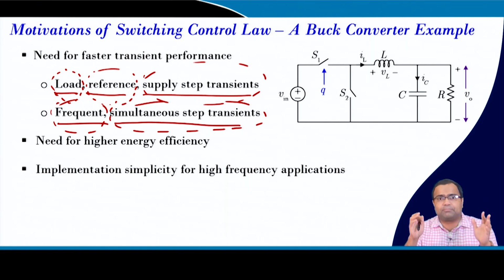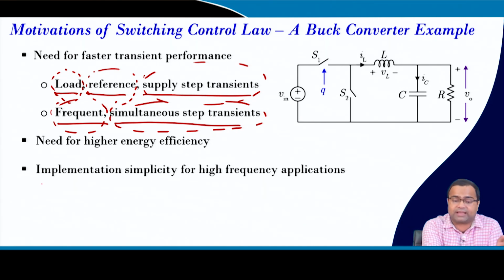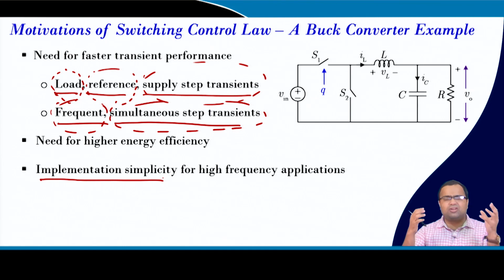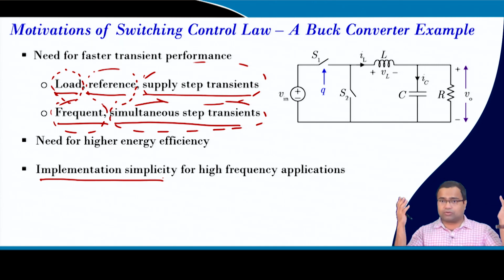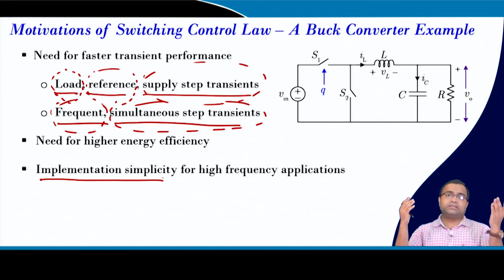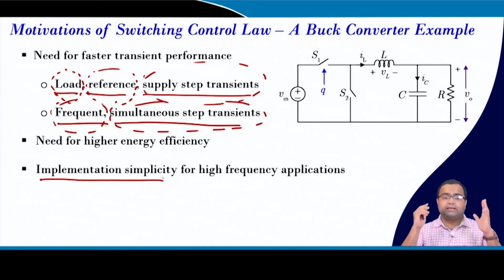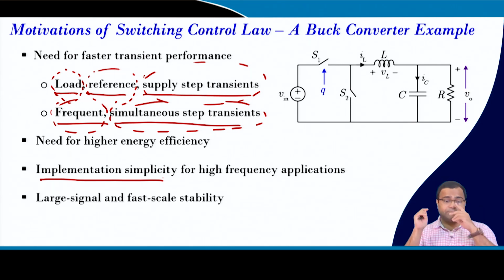It should not take much resources, because ultimately it comes in terms of price. If the control logic is complex, then it may require more transistors or resources at the IC level, and that will increase the silicon area and that will increase the cost. So the complexity will come in terms of price and also in terms of power consumption. So we need to make the design simple, implementation simple.